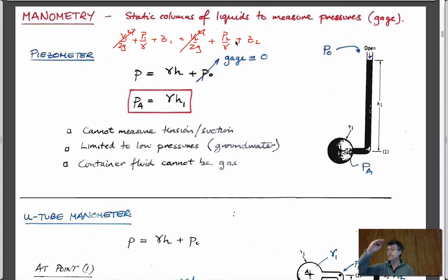And so those differences in pressures as you go up and down just become the manometer rules. Z1 minus Z2 is just a change in height. So in other words, this expression goes to be Z1 minus Z2 is equal to P2 minus P1 over unit weight. And so if we just multiply this by unit weight, then this is no different. This is delta P, the change in pressure you get as a change in elevation multiplied by a unit weight. And so that's just the manometer rules. So perhaps it's interesting to think that obviously Bernoulli gives you that. If you go up in a fluid, then you change pressure by whatever the height changes multiplied by the unit weight. If you go up, you subtract the pressure. If you go down, you add the pressure.